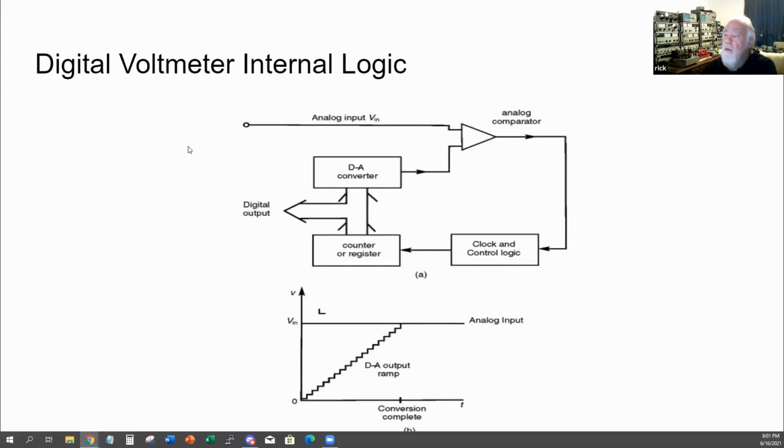So moving that rotary switch on your meter actually changes an input to the computer in your digital voltmeter, and that moves your decimal point, and it changes the logic that takes this binary value from the comparator and displays the actual voltage by reading this analog voltage and comparing it to that rising voltage on the capacitor. You end up with a number that's equal to the voltage that you measured.